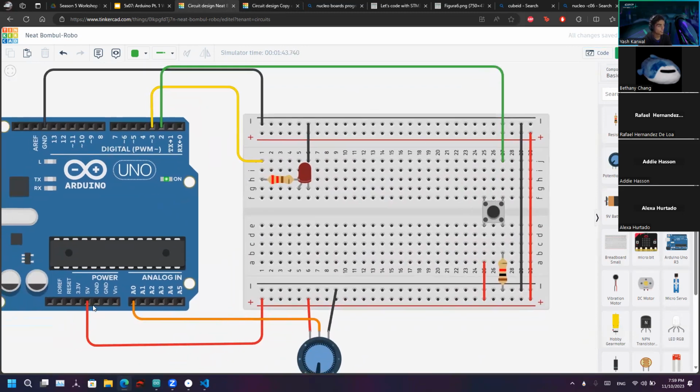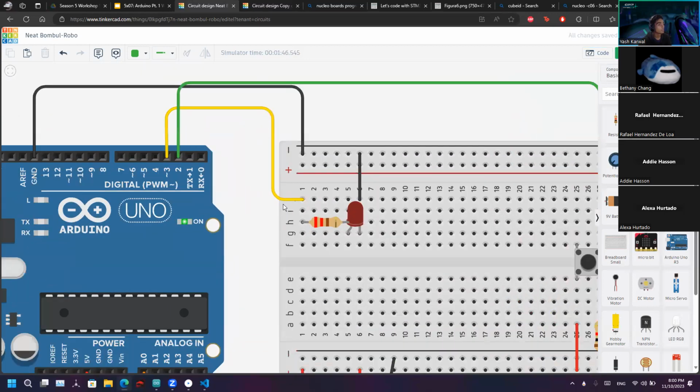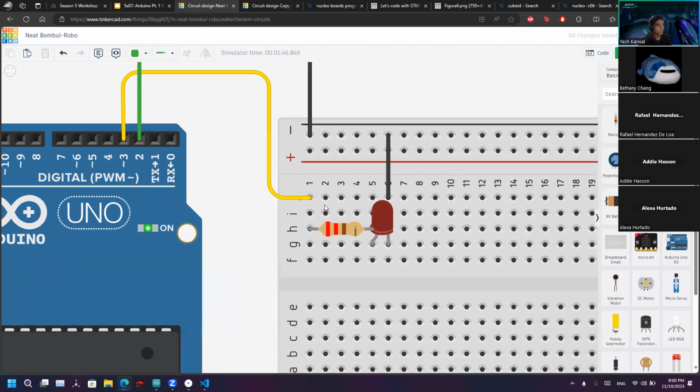So here, for the 5 volts on this rail right here, this rail goes across the entire thing. And then I put this red wire right here that goes to this other rail that goes all the way across, right? That's your main 5 power. Same for the ground. The ground goes all the way across. So both rails, power and ground, I'm talking about these rails right here.